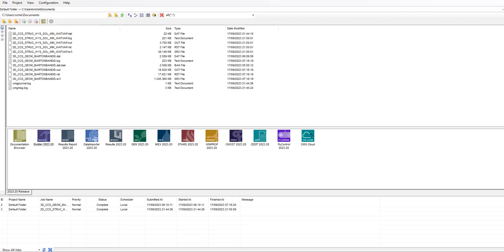In this video, we will continue our learning on CO2 sequestration modeling using CMG software. In the previous video, we completed the run with GEM, where we include water vaporization in our model. So we have CO2 injection and, of course, structural trapping. On top of that, we also enable hysteresis trapping, solubility trapping, mineral trapping, and lastly, we incorporate the water vaporization.